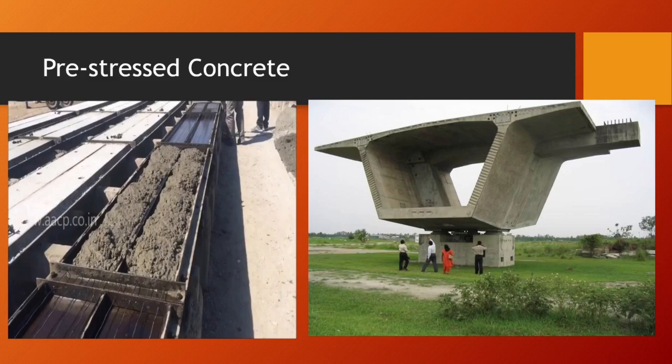On the left hand side here we can see pre-stressed concrete, and if you remember what I said in my drawing in part one, where you can see the reinforcement steel bars. They're hardly bars, they're about 5mm, 6mm in diameter, and you can see that they're connecting all the way through, and then the wires are put through under tension. The concrete's poured in wet like that, and then a tension will be put onto these wires, pulled in an outwards direction, and that's kept under tension until the concrete has gone off, cured completely.